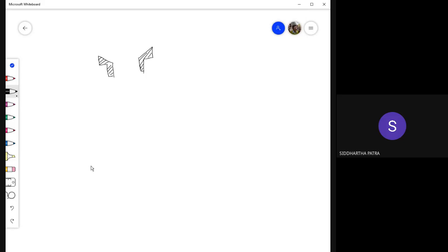Okay. But when you are drawing a detailed drawing, think about what the component actually is. So basically, in the bottom, there is a cylinder, which is this portion. On top of that, there is another cylinder, but the internal surface is actually conical. Okay. So the geometry is something like this, in 3D or in isometric view.